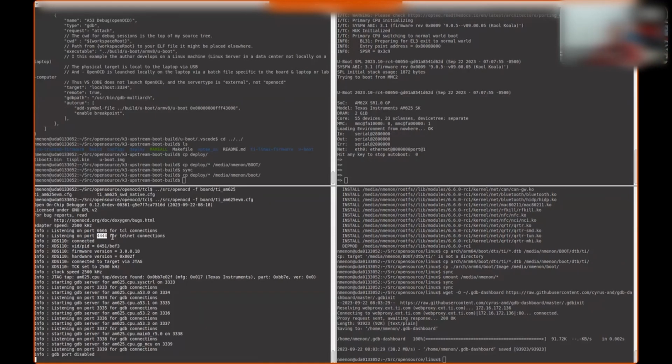Now, that is very useful when your processor has crashed for some reason and is not accessible, or maybe the processor has not even started up. The third case that you could have is that the processor is in, let's say, low power mode. For example, you're debugging the deep sleep path and you don't have access to the processors because you're going down the last stage sequences. So you can use the mem AP port to get inside the SoC from the debug subsystem and look at various peripheral control MMR, PLL registers, I don't know, DDR controller registers, or whatever you would like to debug.